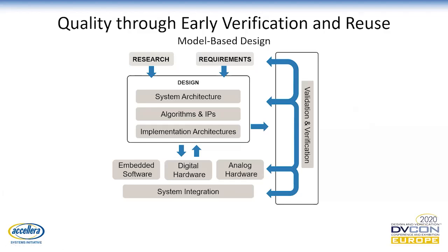So then all models and test benches designed using this approach can then be reused within the traditional EDA tools for analog and digital design. So specifically, we can reuse them in verification. So this applies to design models as well as test bench components. For instance, analog models designed using MATLAB and Simulink can be reused within digital RTL simulators, as well as within analog SPICE simulators. And the same applies to test bench components and for digital models.